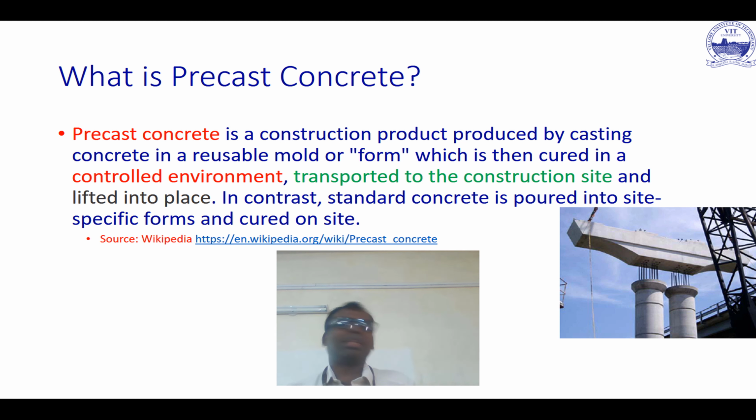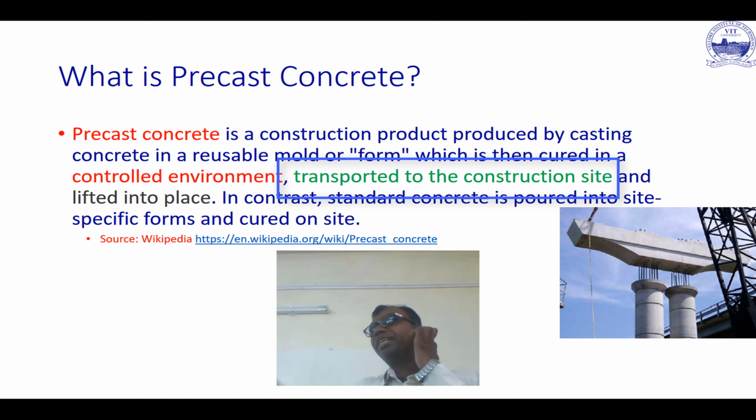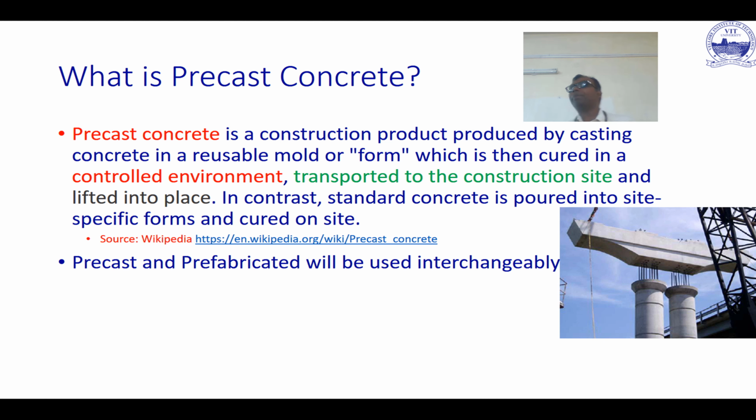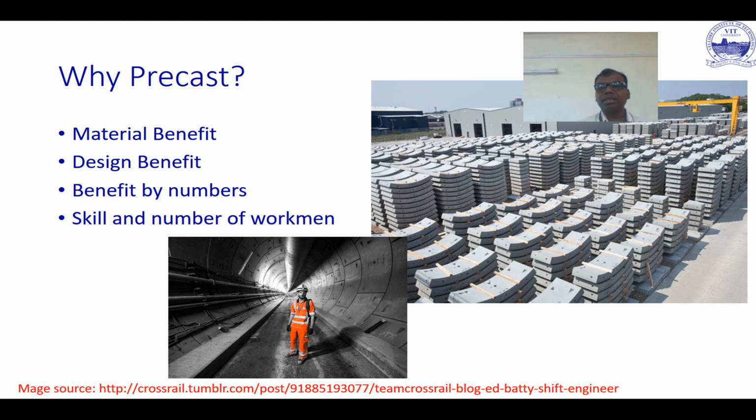Another important thing is that you can adopt advanced curing techniques like steam curing and stuff like that, which is very difficult to do on the site. Not impossible, but it's very difficult. Then you transport it to the place where you want to keep it and lift it and place it into position. So there are three stages. First you cast it, you transport it, and then you lift it and keep it in place. Okay. Now I'll be using precast and prefabricated interchangeably in the classroom. So suppose I say precast or prefabricated, it's going to mean the same.